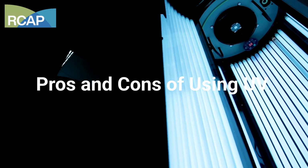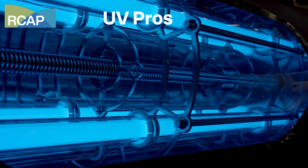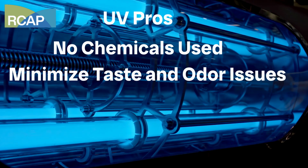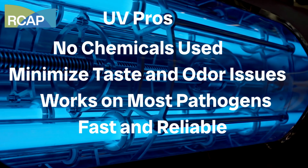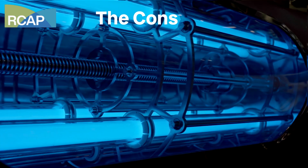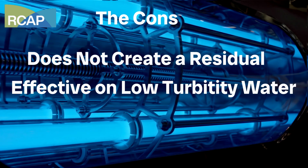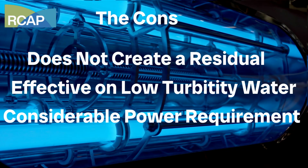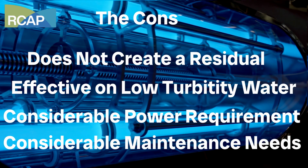Now, we shall look at the pros and cons of using ultraviolet disinfection. The pros of using it include that ultraviolet disinfection uses no chemicals that may cause taste or odor issues. It is effective against a wide range of pathogens, and it is fast and reliable. The cons include that the use of ultraviolet disinfection does not create a residual in the distribution system, is really only effective for low turbidity water, it requires a considerable amount of power to operate, and requires a significant amount of maintenance to ensure that it continues to work properly.